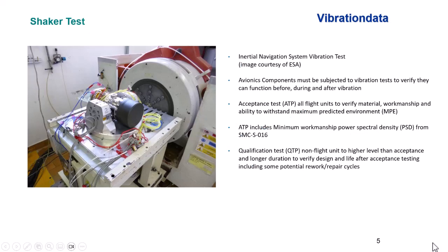So here we've got an electromagnetic shaker. So you see this cylindrical structure here. Now normally that would be upright. It's a uniaxial vibration machine. But in this case, it's been rotated 90 degrees. It's been attached to the slip table through bolts. And this is so that the shaker system can apply a lateral base excitation to this component.